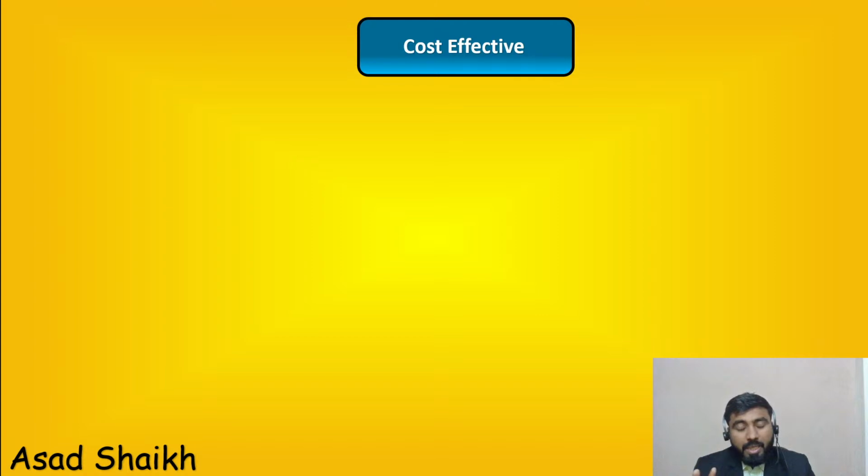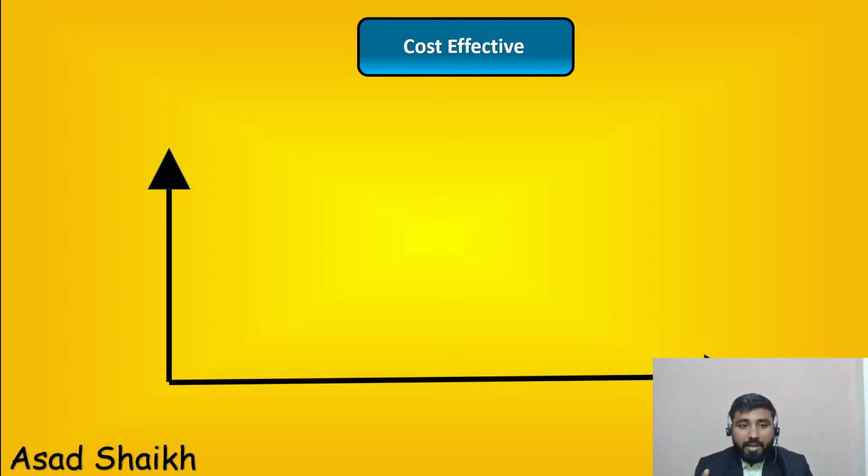We'll keep segmented ball valves and plug valves, plus globe valves and butterfly valves, because these are usually the four types used for control applications. For special applications you have diaphragm seals and diaphragm type valves, but those are for very high viscous applications and very specific industry related stuff. So let us first discuss this overall as a graph.